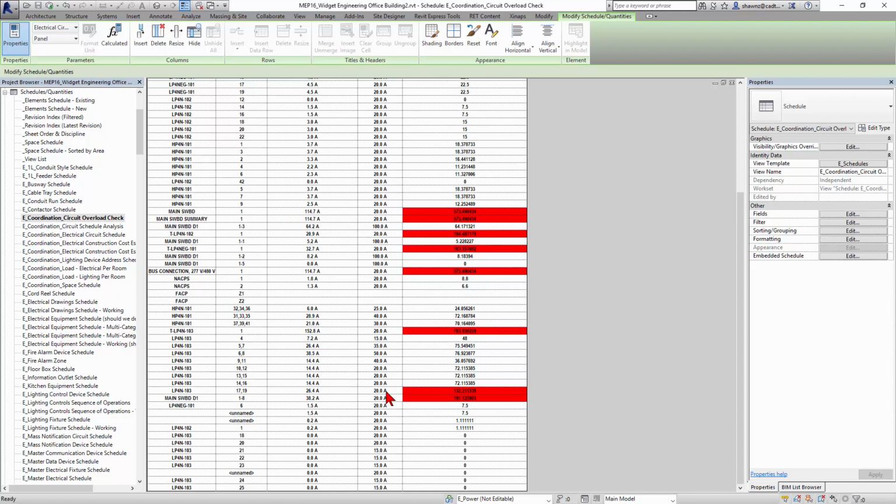Like right down here, I've got this panel where I have a 26.4 amp load on it. Well, maybe I want to increase that. I want to make that 25 amps. Now I'd have to tab through into that circuit to find that information out. In this case, you can see as I go to 25 amp, I'm still not quite meeting that 80% rate. In fact, I'm under the load still. I need to go to 30 amps perhaps. So if I go to 30 amp, I'm at 88% of the actual load on that circuit. So I'm still too small of a breaker in this case. So maybe I want to jump to a 35 amp or a 40 amp breaker. And when I do that, I get the non-red line over here telling me, yep, you're good to go.